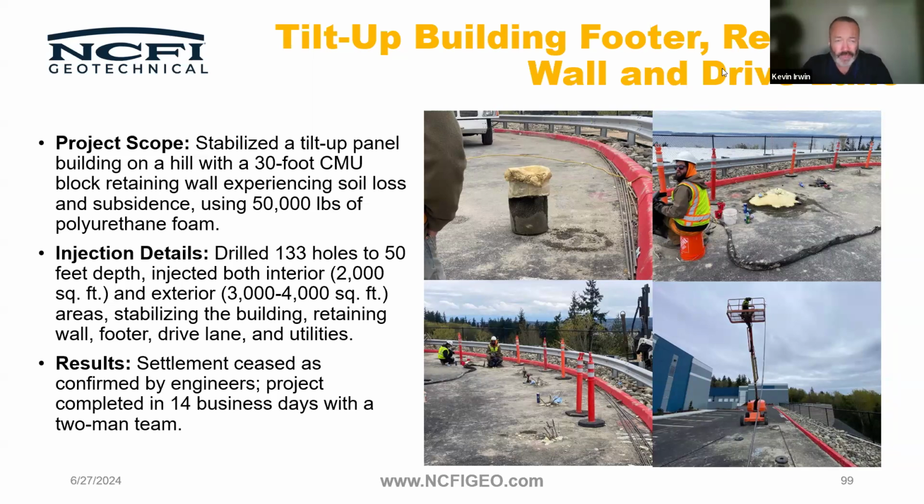I am not aware of any soil that we would say no. Tom or Robert, you heard of? Not necessarily. What we have to look at is the actual soils reports and determine, is it viable? You're not going to get foam to expand into 30 blow count material. We're looking for kind of weight of hammer. A good rule is kind of that single digit weight of hammer to 9 blow count material. Doesn't matter what material it is.